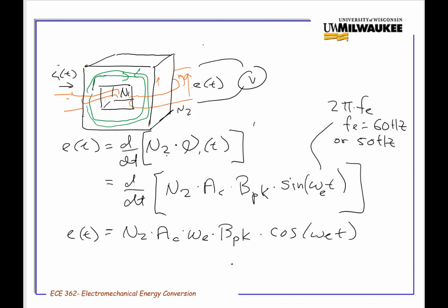So you got some meter like a Fluke RMS meter, or you might have this instrumented up with a Yokogawa power meter or something like that, to look at voltages, currents, and they're going to all be measuring RMS quantities.